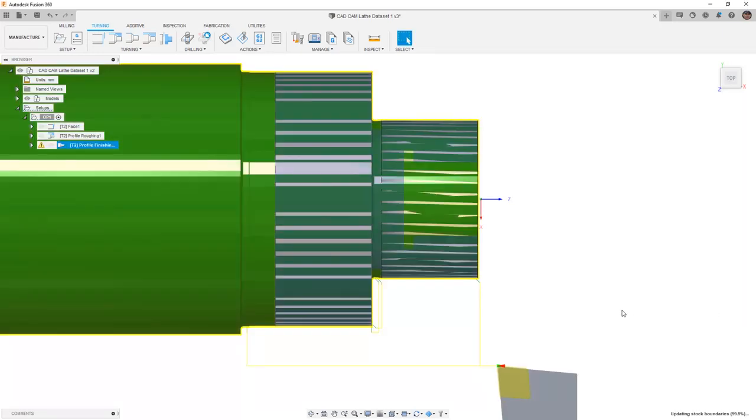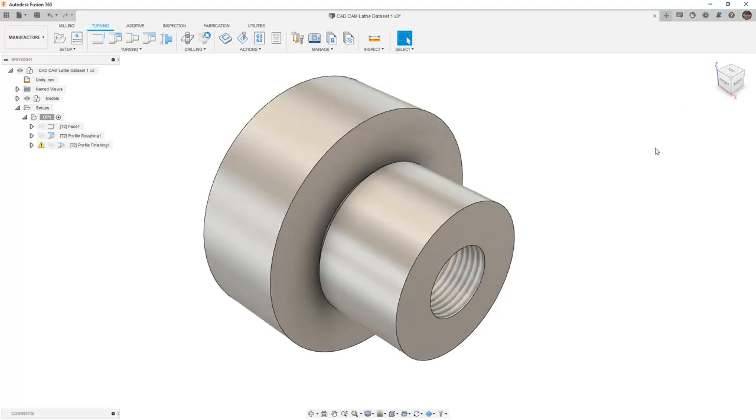So now it's creating a finishing cut going down to our final depth. You can see it's leading into this cut. It's pulling away because we're using no dragging on this face, and then it's creating one final cut to go along this outside edge, going to 8 millimeters past the back of our part. From here, let's go back to a home view, and let's do a quick save before we address the warning in our browser.